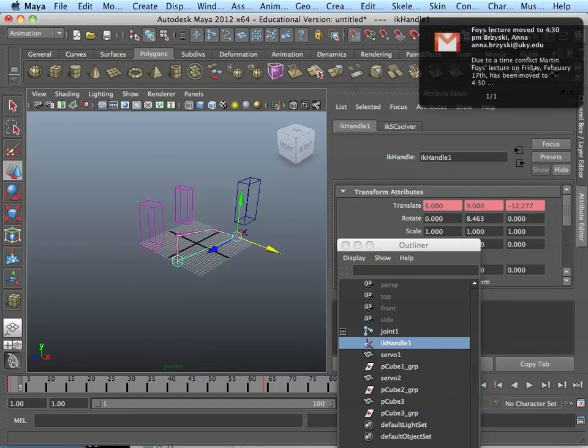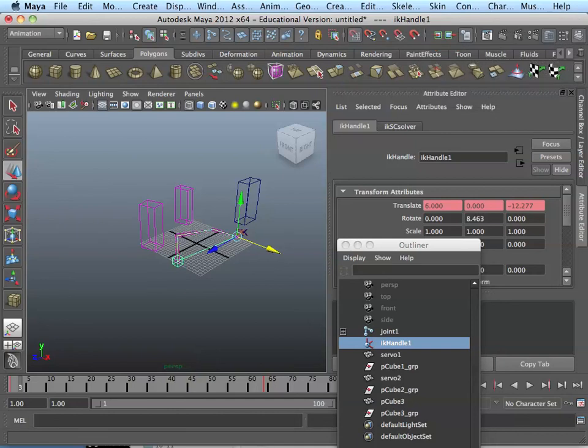So I'm going to plop the servo down the board. This one, again, is white, red, black. White's the signal, red's positive, black's ground. So first things first, move it over here so it's easy to get to. I know from the code that it's going to be servo 2. Servo goes to the 2, goes to the next pin there.